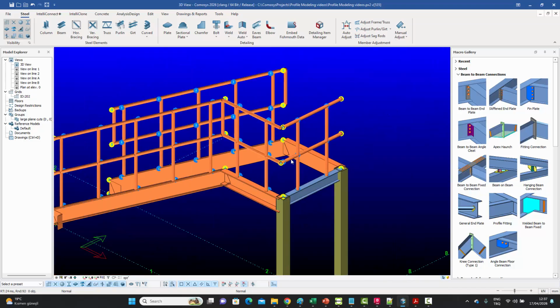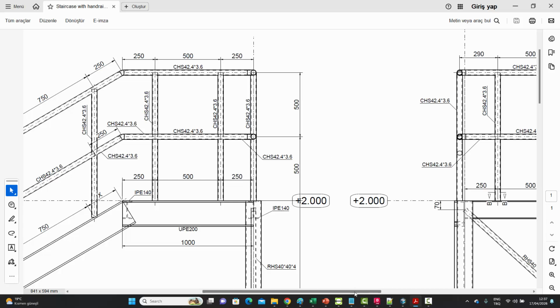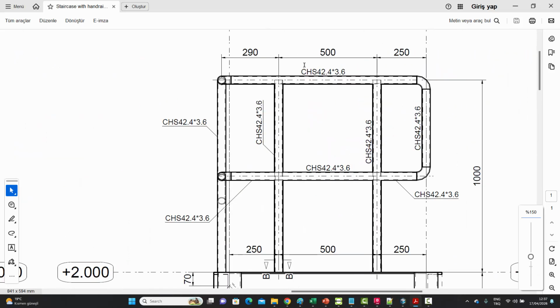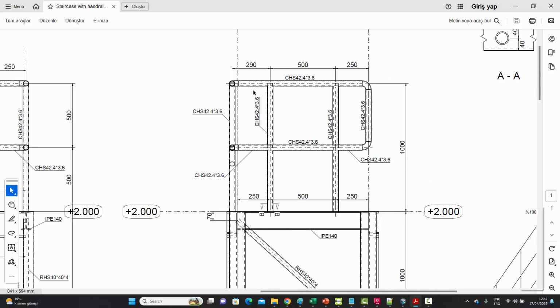The reason why I did minus 290 over here was, if I go back to the drawing, on this side, you can see that these pieces are actually extended beyond the axis, which is the 250 point. And the reason why they do that is because the vertical ones are sitting on the stringers with the offset of 40. So 250 plus 40 will be 290. So they need to be extended about 290 to get to that point.